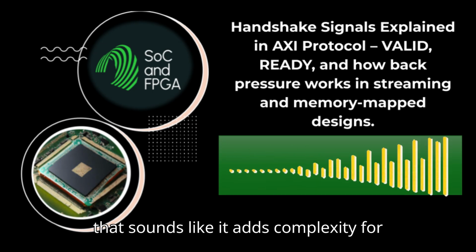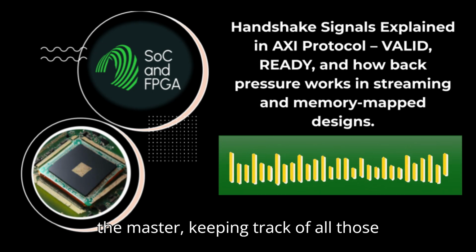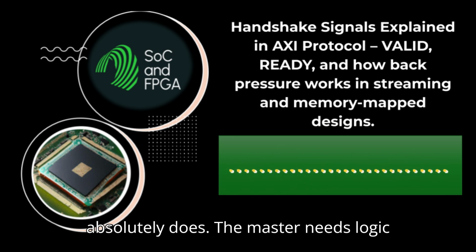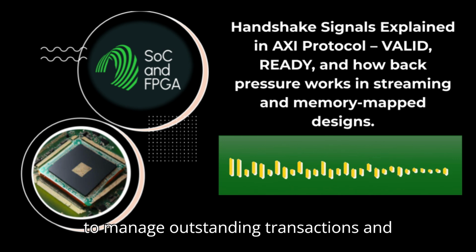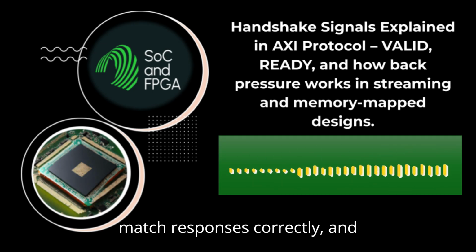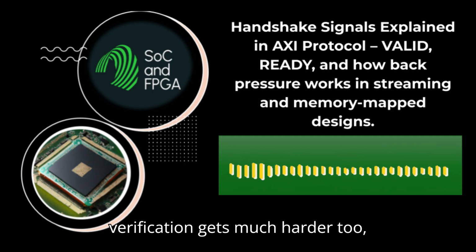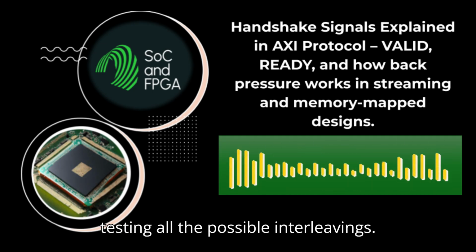But that sounds like it adds complexity for the master, keeping track of all those IDs and out-of-order responses. It absolutely does. The master needs logic to manage outstanding transactions and match responses correctly, and verification gets much harder too, testing all the possible interleavings.